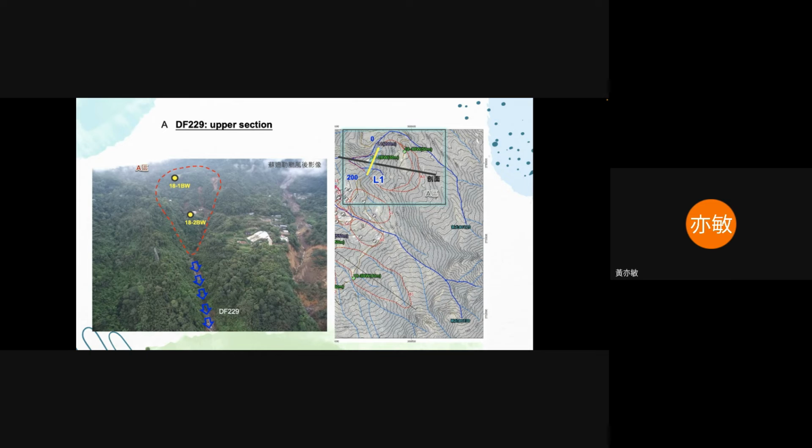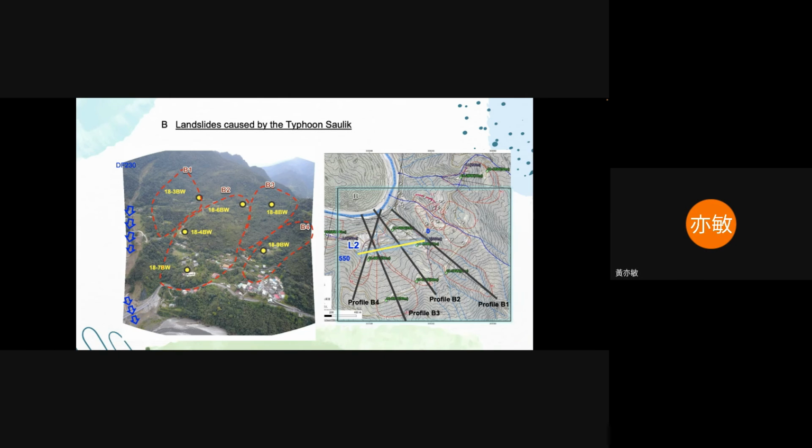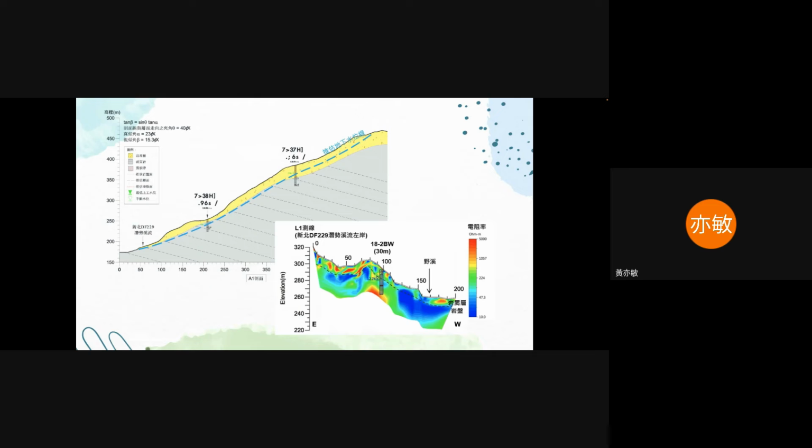This is the on-site photos. We take aerial photos from the UAV. We cannot identify directly by our eyes there could be potential landslide areas. This is another view of zone B. And we also have the information about the water. We want to know the groundwater table, the underground water table, because it will affect the safety of the landslide.